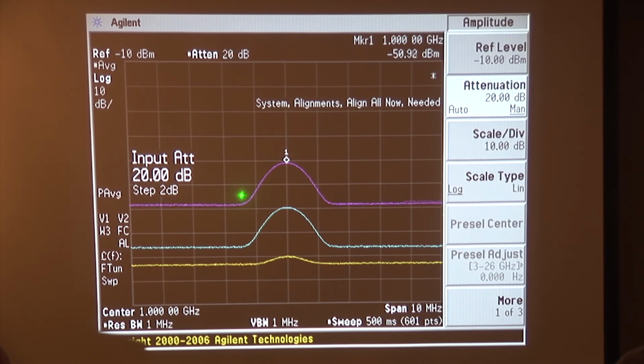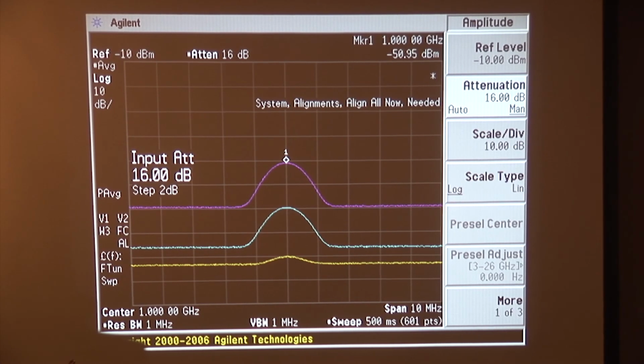So the sweet point here, where we kind of optimize our signal to noise ratio, but we're also optimizing dynamic range, is at about 16 to 18 dB, just like we did with the manual attenuators. Perfect. Optimum for signal to noise ratio and optimum in terms of dynamic range if you're trying to optimize both variables simultaneously, as opposed to if you were trying to optimize just one or the other.